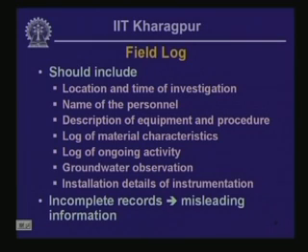For this purpose, particularly when an investigation is undertaken for a detailed project design stage, it is essential to have the locations of investigation properly surveyed in terms of their top elevation, or the elevation of the ground surface at the location of the investigation, as well as the exact location of the investigation referenced to some benchmarks or surveying monuments, or in terms of GPS coordinates.